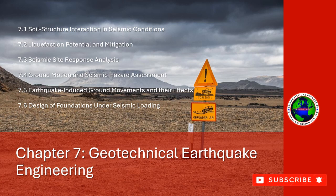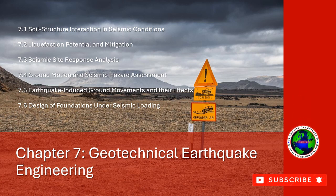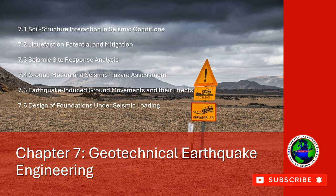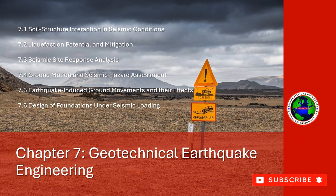7.2.1 Causes and mechanisms of liquefaction. Liquefaction occurs when the pore water pressure in saturated soils increases during seismic shaking, reducing the effective stress between soil particles. As a result, the soil loses its ability to resist shear forces, and the soil mass behaves like a liquid. The primary causes of liquefaction include 1.